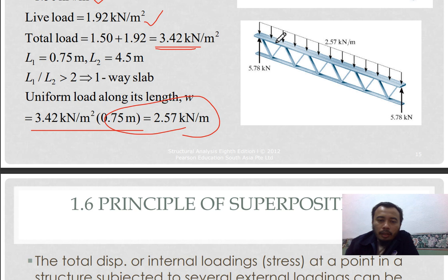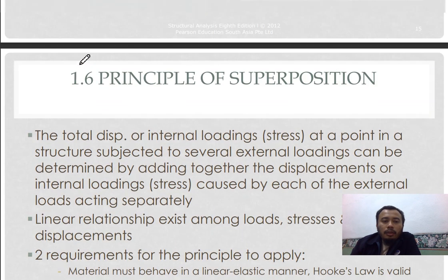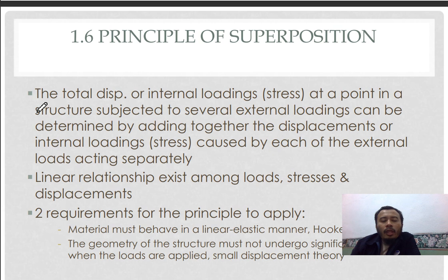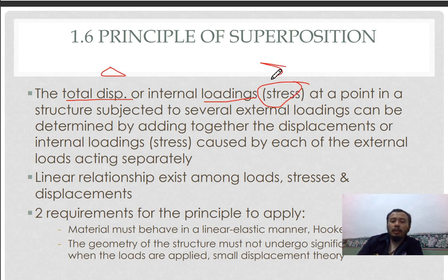After we have analyzed the loading, we can calculate the reactions. The principle of superposition. This is the next subtopic. Principle of superposition: the total displacement or internal loadings at a point in a structure subjected to several external loadings can be determined. So you want to determine the displacement or stress at a point, let's say point A, in a structure subjected to several loads.